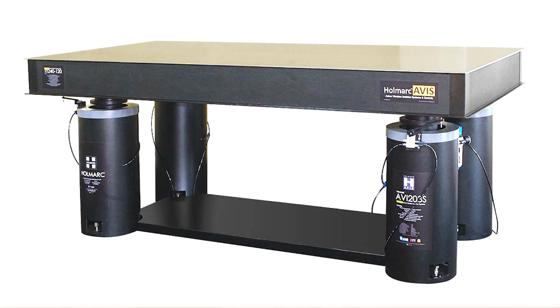When passive isolation systems prove insufficient, consideration is then given to active vibration control systems, wherein sensors and electric, pneumatic, or hydraulic actuators controlled by a processor counter the vibration. Although more expensive than passive isolation systems, these active systems can control both vibration feeding into the instrument from outside and vibration produced by the machine itself.